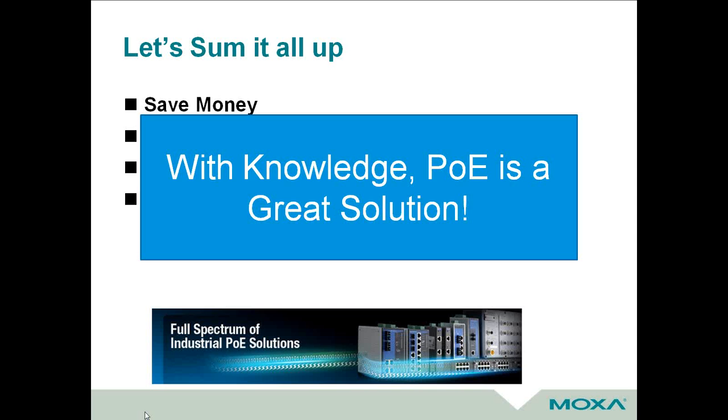Are all standards-based PoE 48 volts? Well, traditionally, PoE as it relates to 802.3af and 802.3at is 48 volt DC, and that is considered the standard. There were some substandard things that did 24 volt DC, but again, they can call it PoE. They just can't call it 802.3at or 802.3af, which is the standard for all PoE.